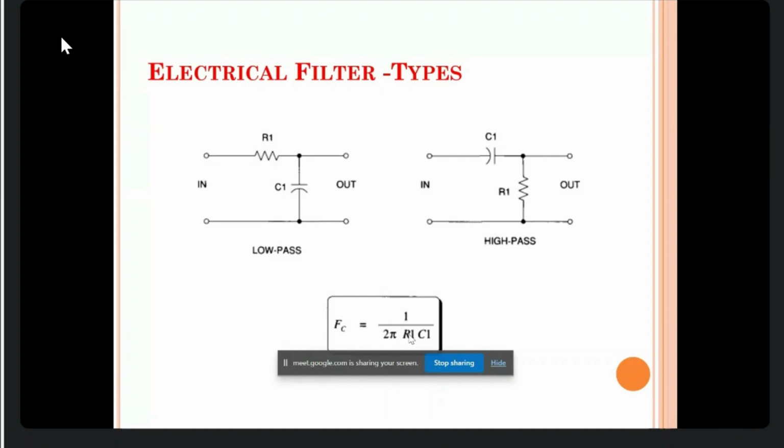So when the inductor or capacitor component becomes very small and comparable to the wavelength, it will also radiate or couple noise, and also give electromagnetic interference, component interference or crosstalk. Like that, many other problems will come. So that is one reason the normal component cannot be used at microwave frequency, a normal LC or RC filter. Another question is, why can't you use an op-amp based filter?